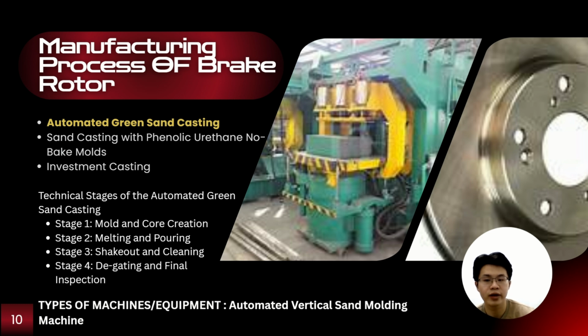For this process, we create a mold using a pattern, and the sand is tightly compacted and highly reusable because of the green sand. After that, we melt down the iron and pour the liquid directly into the sand mold. Once the metal cools and solidifies into the rotor shape, we shake the sand off, clean the surface, and then it goes through the final quality inspection. This is an incredibly fast automated way to create a complex heavy-duty part like a brake rotor.